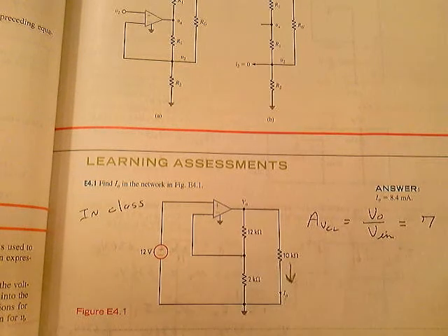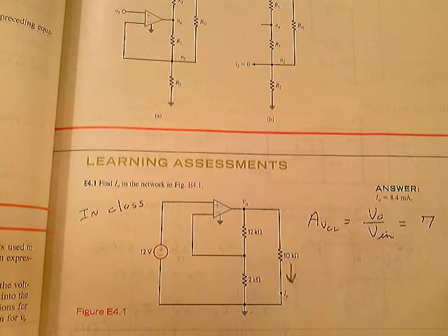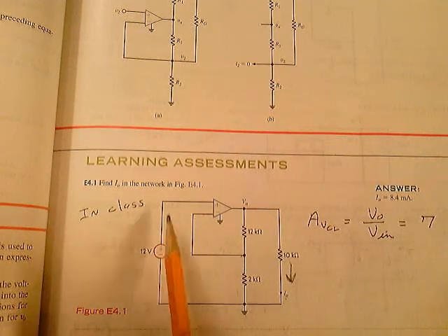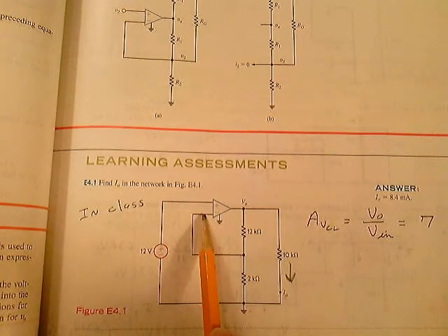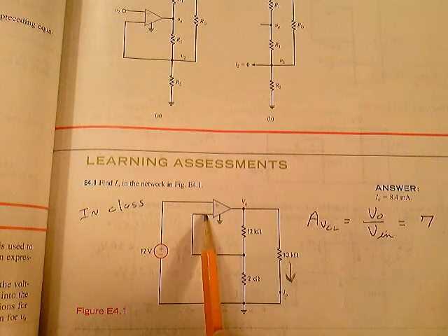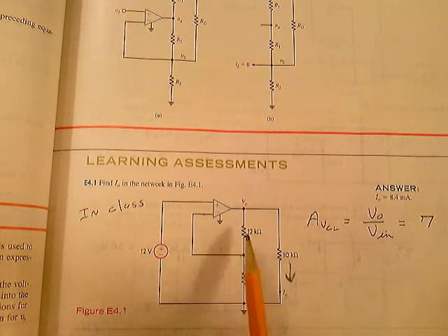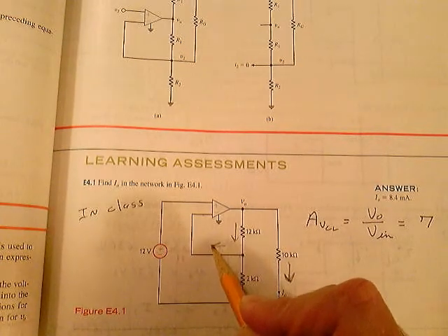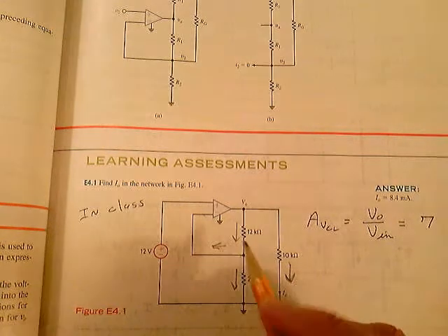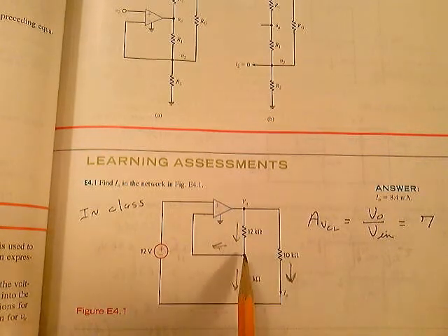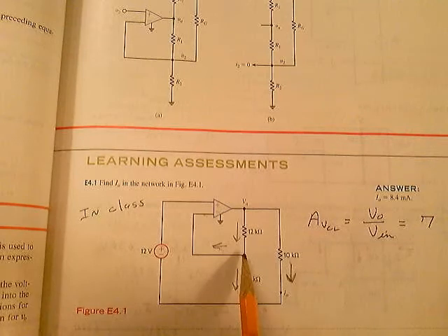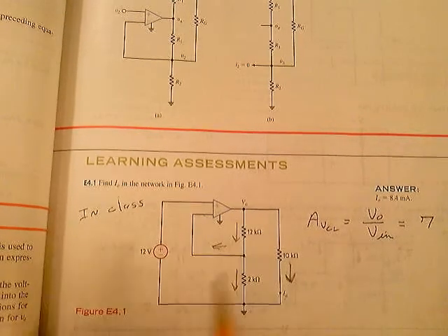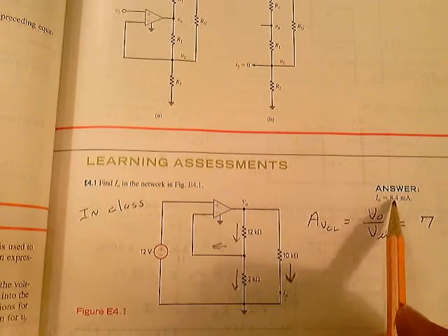Now, if you want to take the previous procedure that I've shown you on the previous page, you want to take this 12 volts and project it down to here, which puts 12 volts down here. You want to assign 3 currents here, maybe a current in that direction, a current in that direction, and a current in this direction. You want to use Kirchhoff's current law and write a nodal equation at that point, and solve for V out, and take V out and divide it by 10K to give you I out. You can get your 8.4 milliamps.